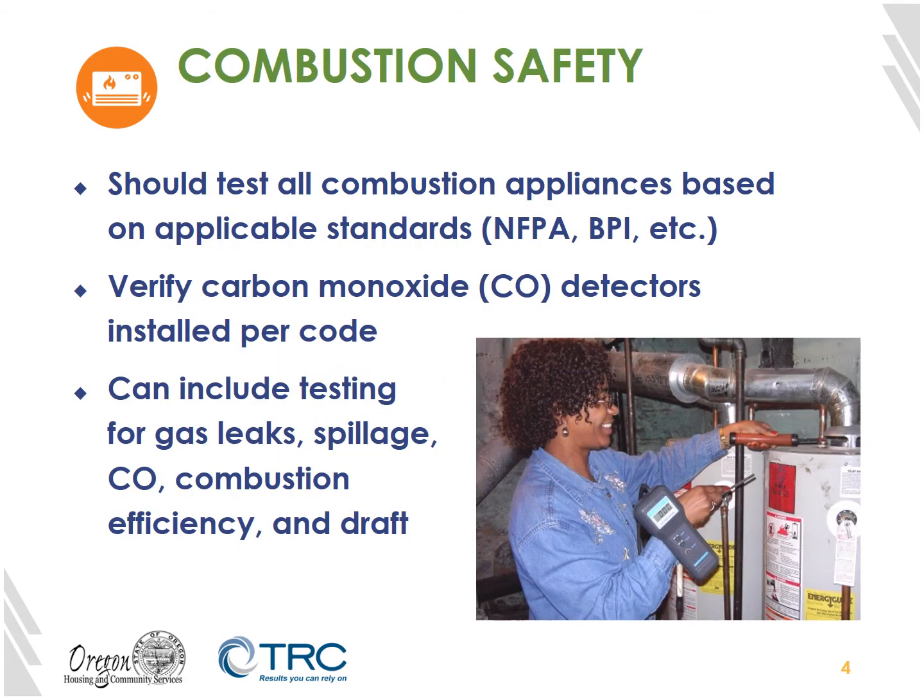If we do have combustion equipment in our building, we need to ensure that we're regularly completing combustion safety testing. We should test all combustion appliances based on applicable standards, such as NFPA or BPI. We need to verify that we have carbon monoxide or CO detectors installed per code, and the combustion safety testing we might do could include testing for gas leaks, spillage, carbon monoxide, combustion efficiency, and draft.